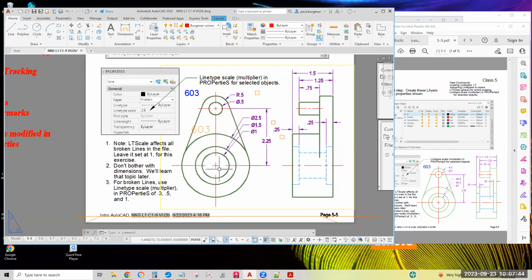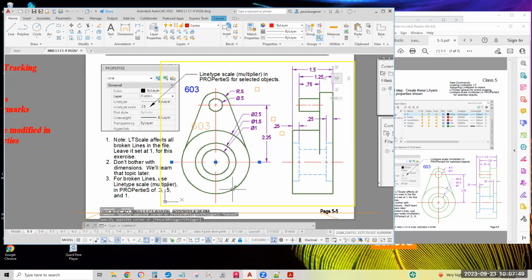You probably won't get them looking exactly like mine, because this one's still left over from when I was using 3 layers of center lines and altering LT scale for the entire drawing, which would work provided your smallest circle is greater than maybe 1/6 or 1/7 of the largest circle. It doesn't appear to be the case, so I might have to study what I did.